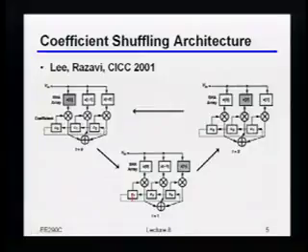Okay, and so you can imagine I can keep doing this rotation, and as long as I do the rotation correctly, and in this particular case I have to match the number of samplers to the number of coefficients, then I can build it so that I never have cascades of these sample and holds, right? Because notice I've always just sample and held once. I'm just feeding that sample and held value to a bunch of different multipliers. Okay? Does this kind of make sense to people?